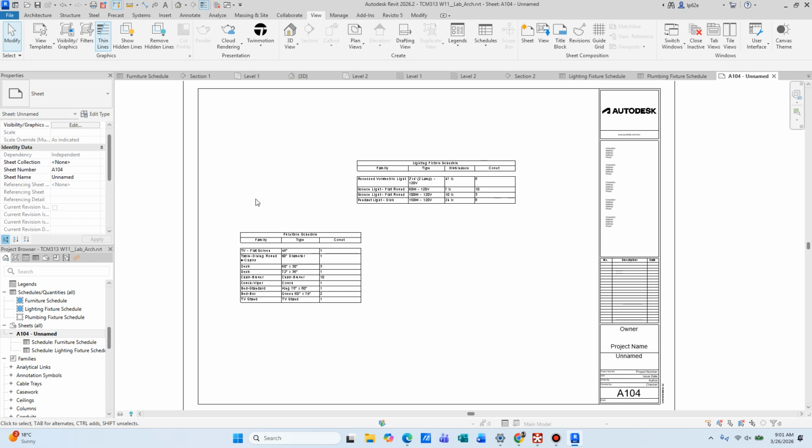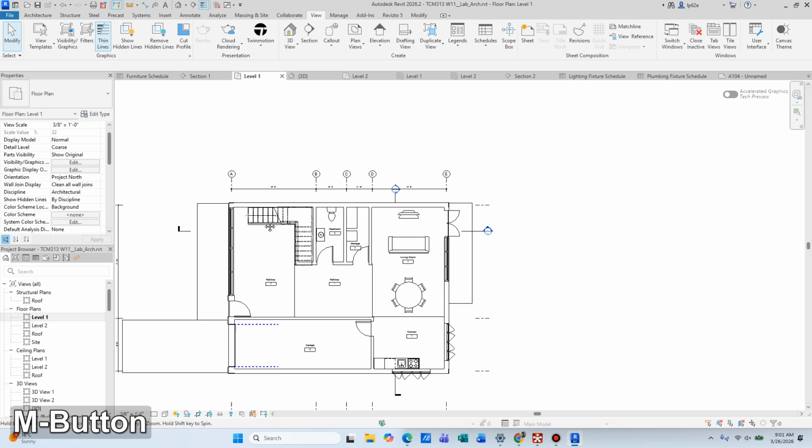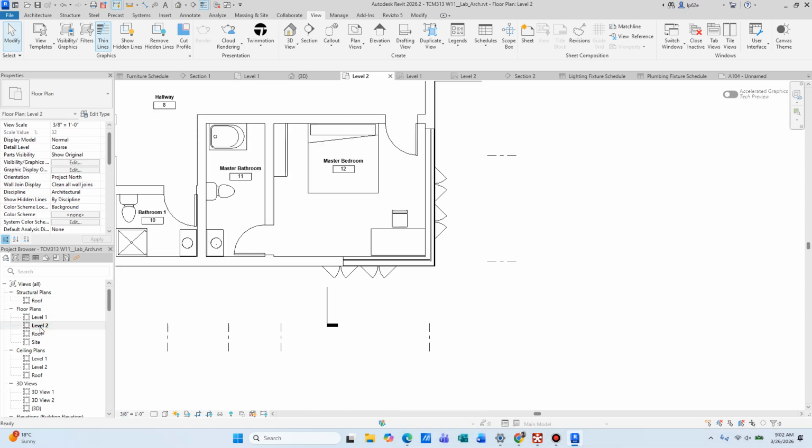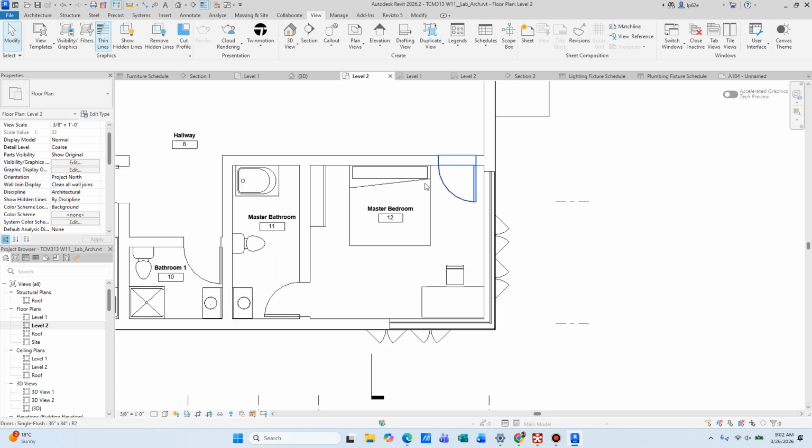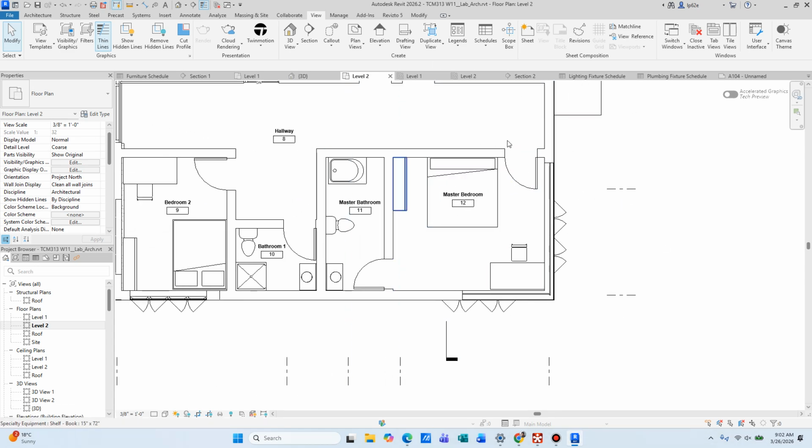All right. Next, the callout views to create the enlarged floor plans and the room section. So, like I said before, callouts or the enlarged callouts are usually used to isolate the view of a specific area inside your building. So let's say that you just want to show the floor plan for the master bedroom. You can use the callout view to do that.